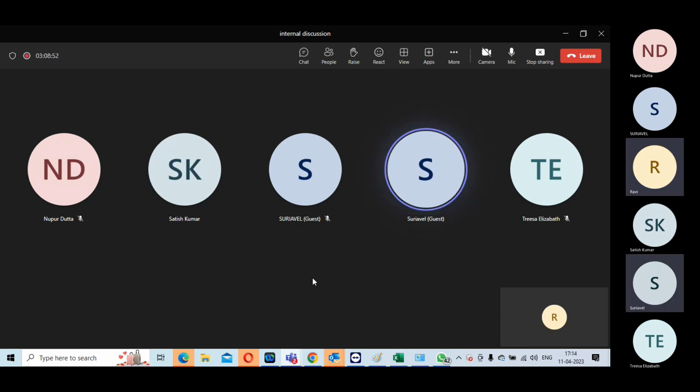Post CTS, you should also enable clock domain based chain reordering, because now it will look at the skew groups and reorder accordingly. If two flops are in different skew groups, then you have a problem, as the skew will be bigger. So skew group based clock chain reordering can be enabled during post CTS, so that hold fixing will add minimum buffers.